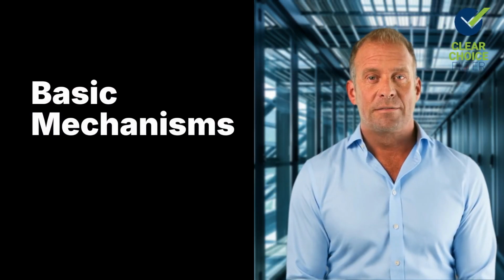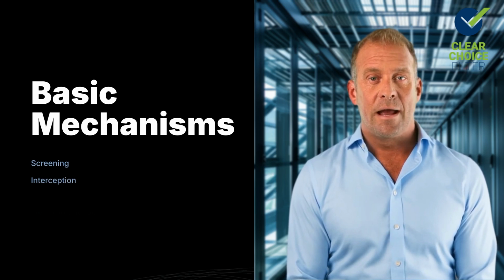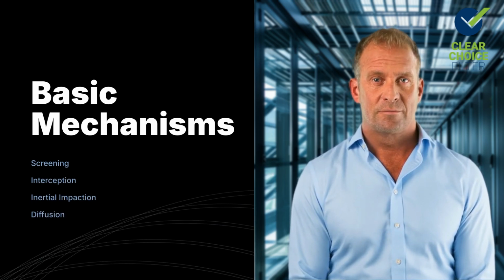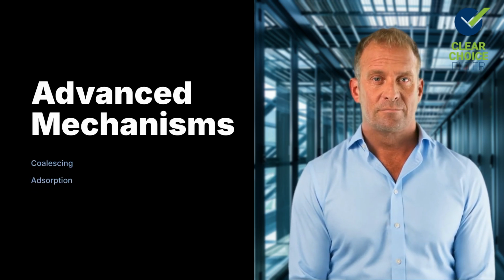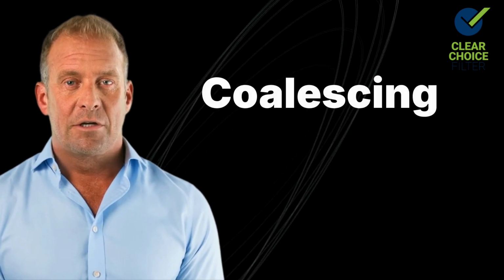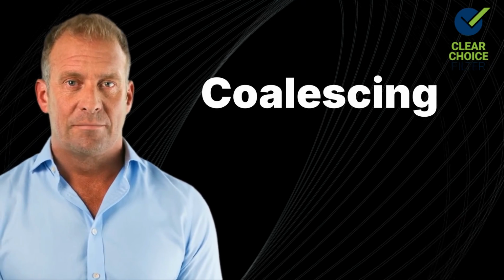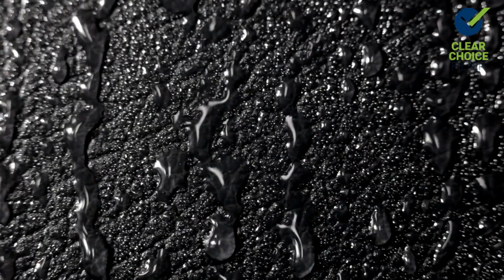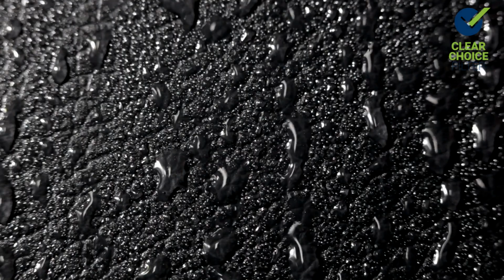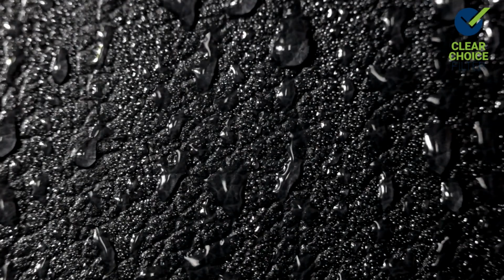We've covered all the basic mechanisms of filtration, being screening, interception, inertial impaction, and diffusion. Now we will move to the advanced filtration mechanisms of coalescing and adsorption. Coalescing filtration is used primarily for removing liquid aerosols from air and gas streams. Fine droplets are captured and merge, coalesce, into larger droplets, which then drain away due to gravity. This method is widely used in compressed air systems and oil mist separators.